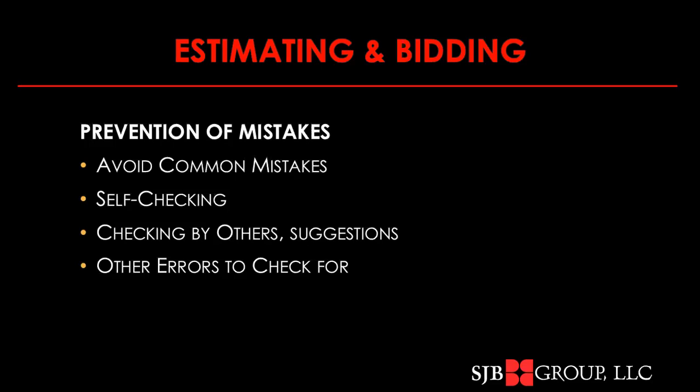Well, the day of bid, or as you get closer to time of bid, you'll probably start getting those last minute quotations in. The subcontractors will be adding or cutting their price. You've got to deal with making those changes in an orderly fashion so that they get done, not duplicated, and the math's done correctly. And you're going to check that again about 2 hours before bid time. And you're going to check it again a half hour before bid time.